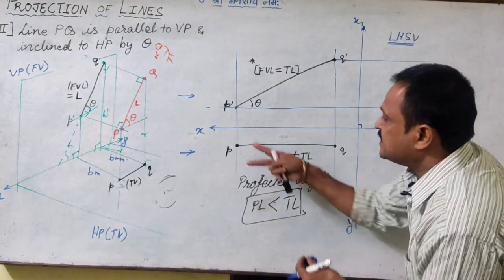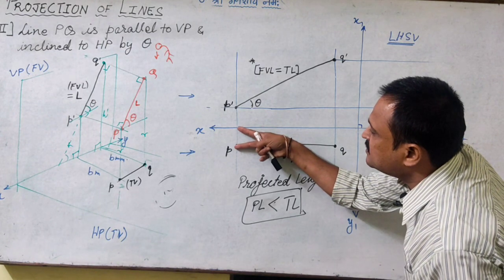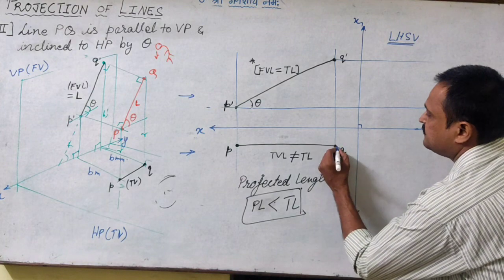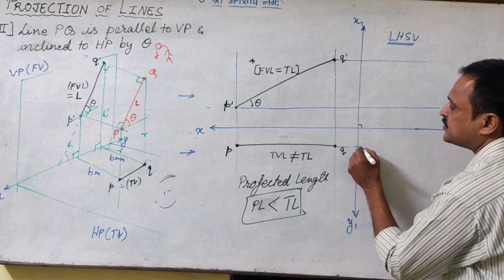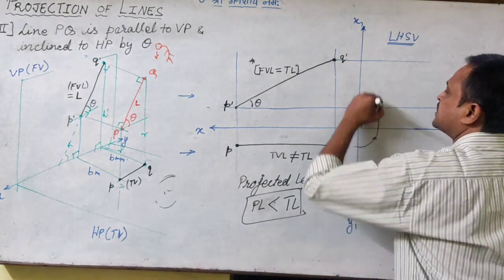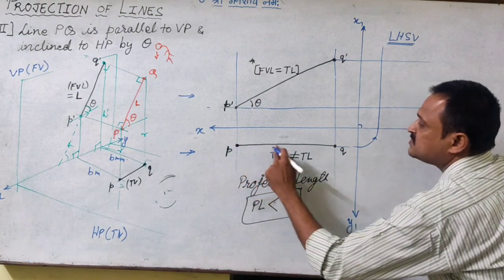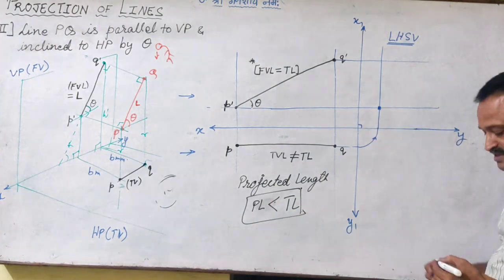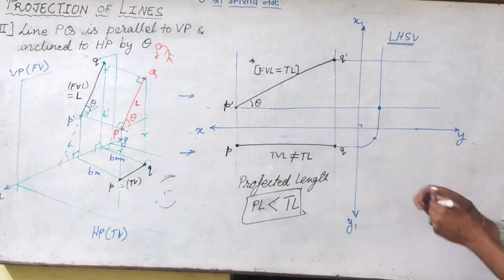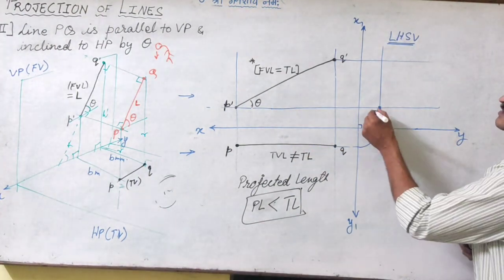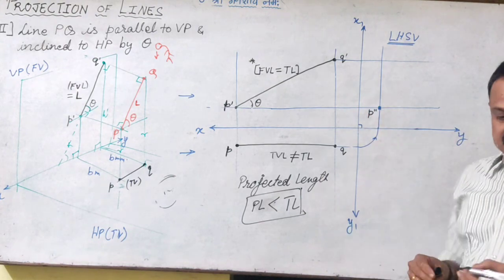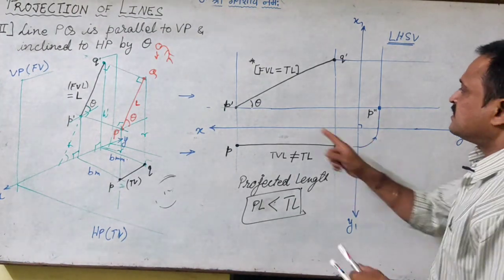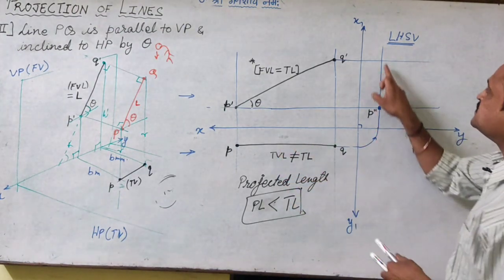Similarly, now I can take the distance of P from the xy, so I drag this till x1, y1 and rotate it and project it. So this is the distance of P. We project wherever it intersects with the height of P. I get this as P double dash, the side view image of the point P. Then Q, I project it.